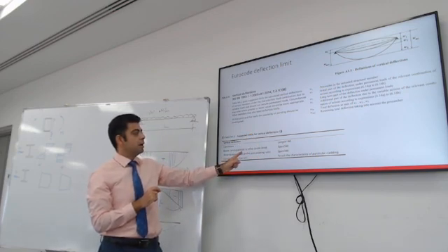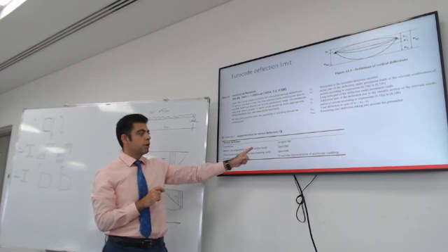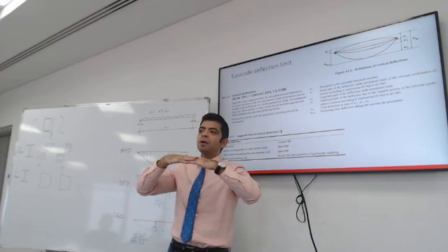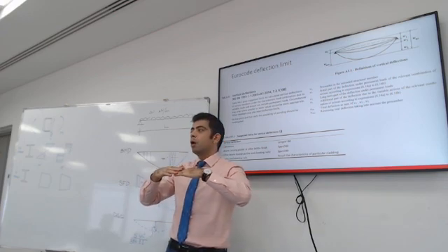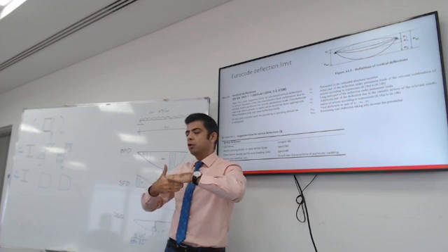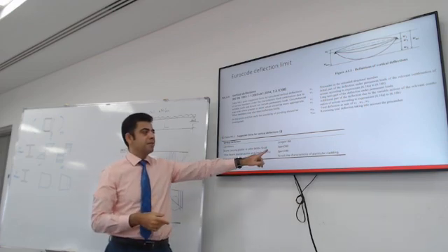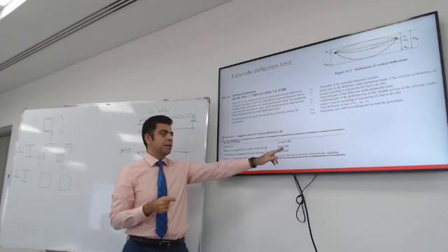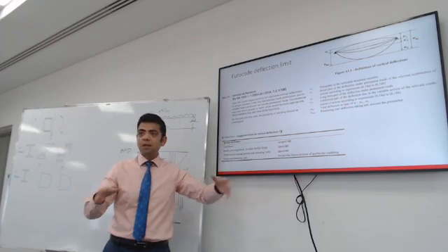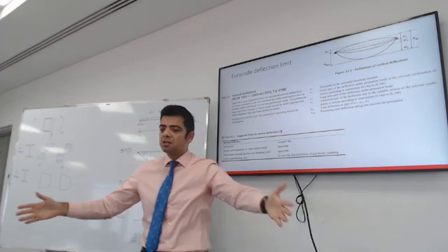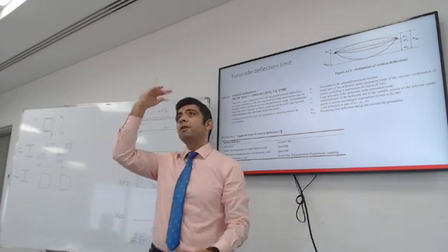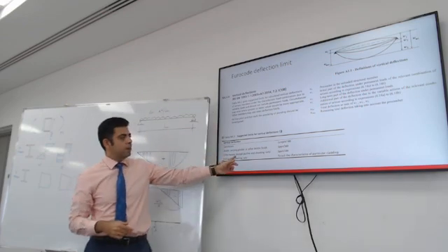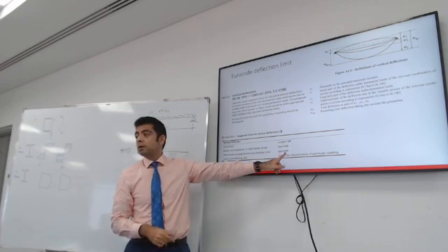Beams carrying plaster or other brittle finishes. So if there is a beam supporting fancy tiles or has a window supported on it, you don't want it to deflect too much, and the maximum deflection would be the span of the beam divided by 360. For most common beams, where there's nothing underneath it and the finishes above it are not very sensitive to deformation, you would use the span divided by 200.